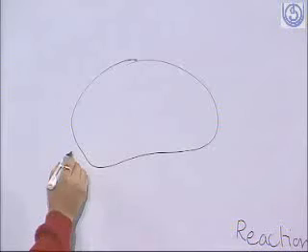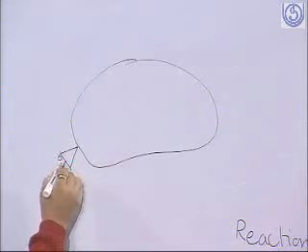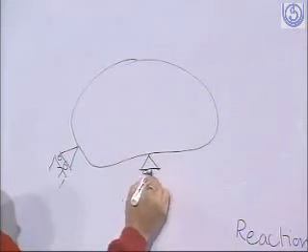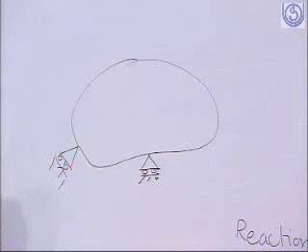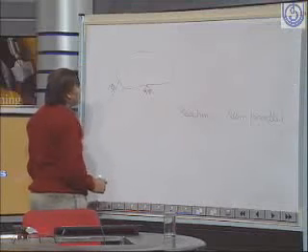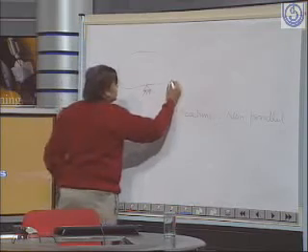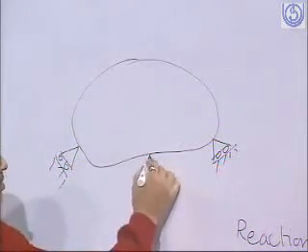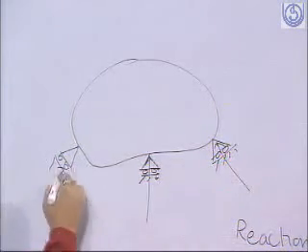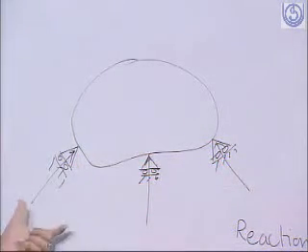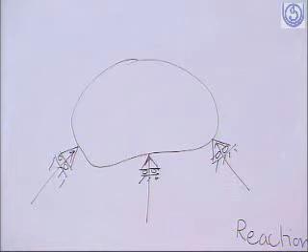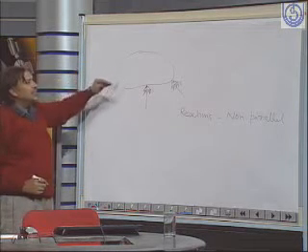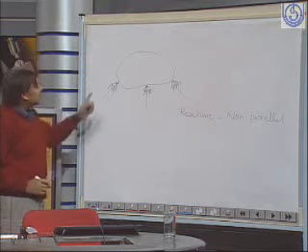So maybe one component you can give from this direction, the other component you can provide in this direction, and other component you can provide in this direction, so that all these reaction components should be non-parallel. They should not be parallel, because if they are parallel, you can provide a force in a perpendicular direction to that, and the structure will not be stable.